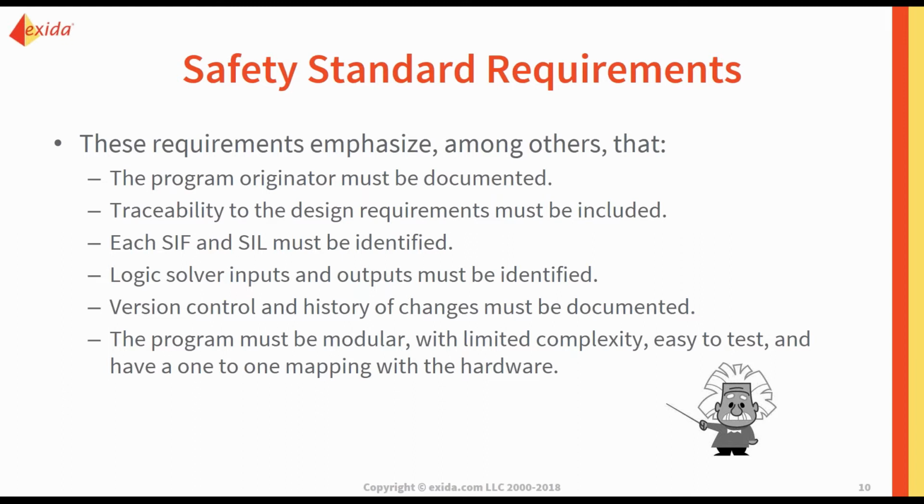There has to be traceability and documentation throughout. So all your design requirements have to be included. Each SIF and its SIL level has to be identified. The inputs and outputs have to be identified and traceable. You're going to need version control and history of changes. And the program must be modular with limited complexity. It's got to be easy to test and have one-to-one mapping with the hardware. So that's a lot to take on.